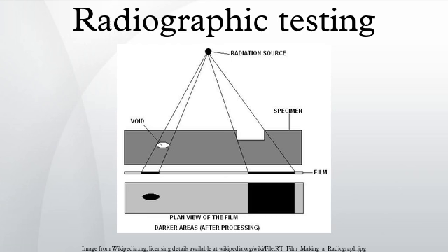Because film is cumulative in its response, relatively weak radiation can be detected by prolonging the exposure until the film can record an image that will be visible after development. The radiograph is examined as a negative, without printing as a positive as in photography. This is because, in printing, some of the detail is always lost and no useful purpose is served.